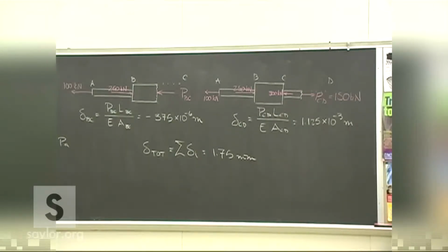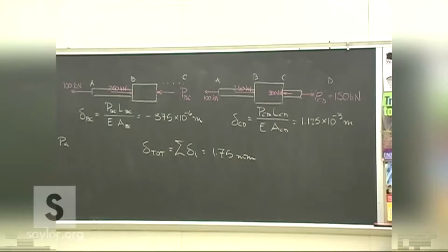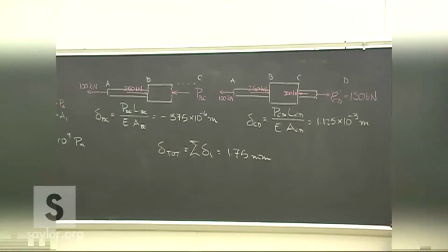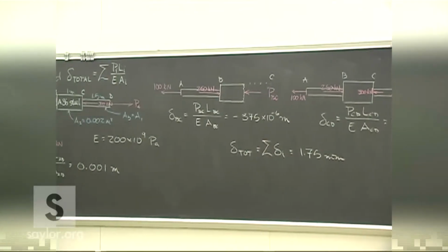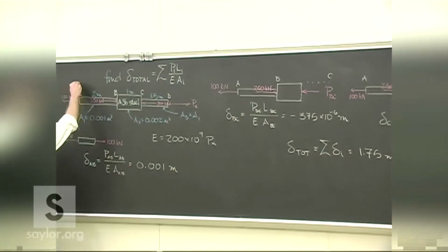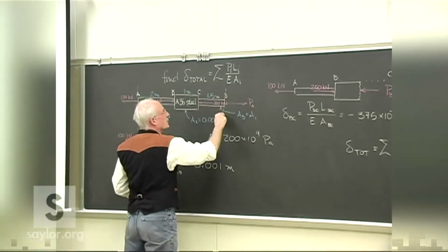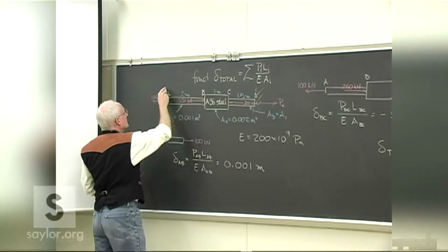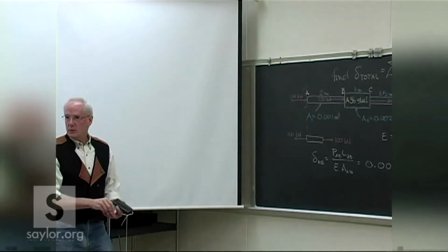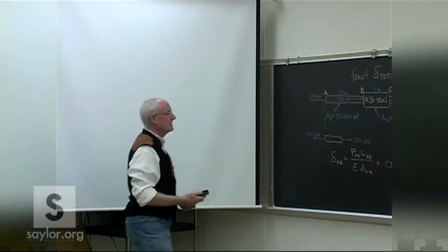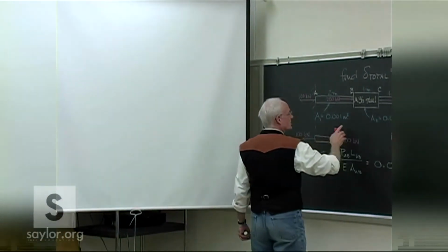So that's what, 15, 16 feet long, and it's changing length. Well, you'd see it. And if this is some part of a structure that's between two rigid supports, it might not be able to withstand that kind of change. So we have to consider all those things.